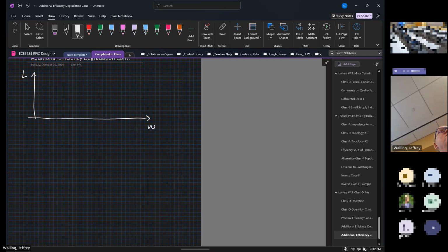So when we talk about self-resonant frequency, you ideally want your inductor to look like that. That allows you to design for it at any frequency using that component. But in reality, when we make this on CMOS, because we have parasitic capacitance, the inductance is going to look something like that. In fact, this thing might look capacitive for a while.